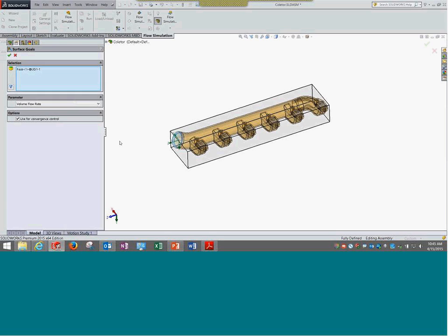So I can create a goal and monitor throughout the solution how it is going. If the results are off, we can go to that particular goal or value. It can be seen as a goal or as a sensor present in the simulation, but a sensor which is not only monitoring but also enforcing certain things in the software, telling it what is most important to converge on. There are more detailed definitions, but at a broader level, this is what I would like to say.